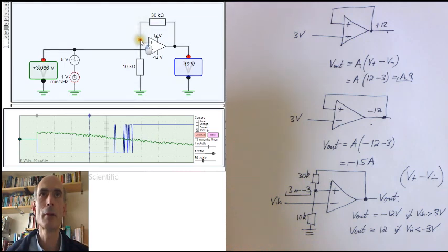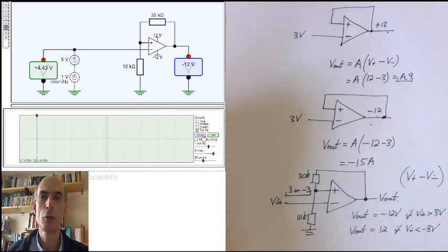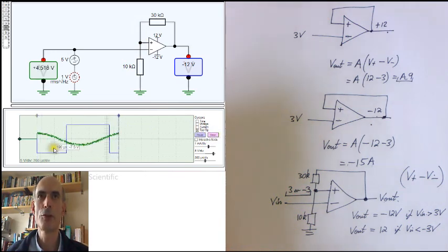Solution: put in our bit of positive feedback, build a Schmitt trigger, and now the noise is not causing any bouncing of the digital signal at all, because the output only goes high when the input gets to below -3 volts, and it doesn't go back low again until the input gets to above +3 volts. Net result, a nice clean digital signal from a rather noisy analog signal.